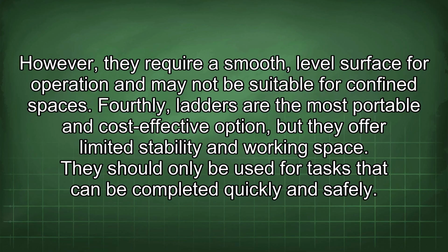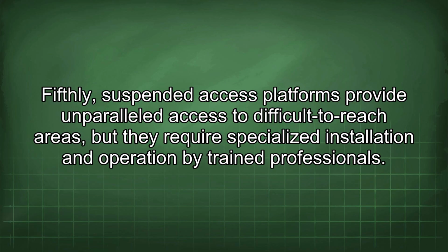Fourthly, ladders are the most portable and cost-effective option, but they offer limited stability and working space. They should only be used for tasks that can be completed quickly and safely. Fifthly, suspended access platforms provide unparalleled access to difficult-to-reach areas, but they require specialized installation and operation by trained professionals.